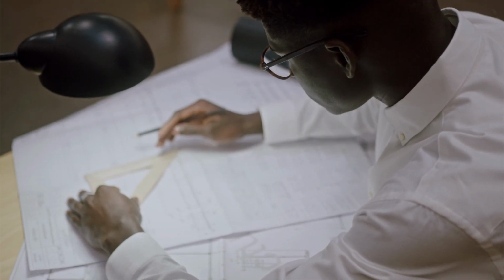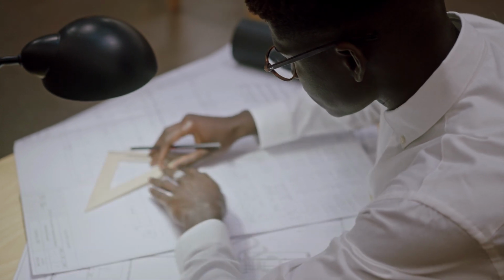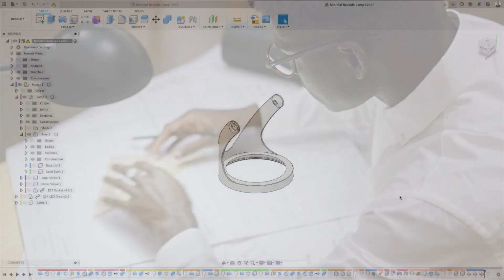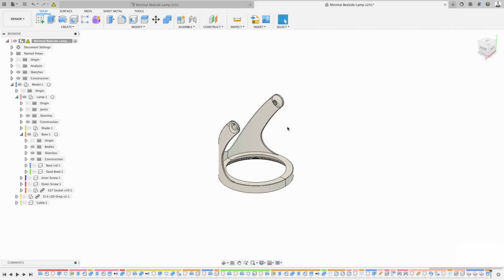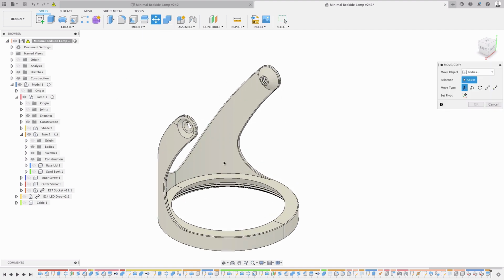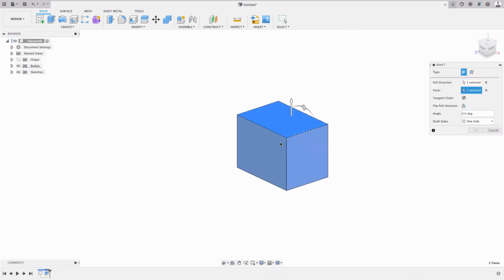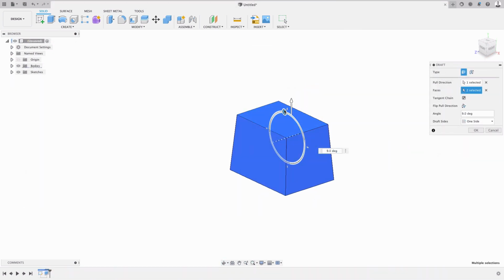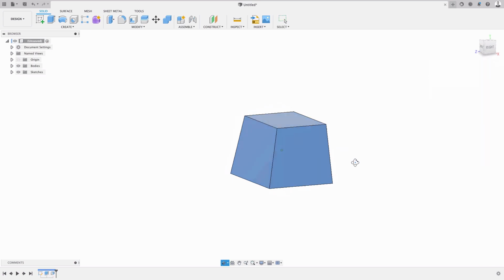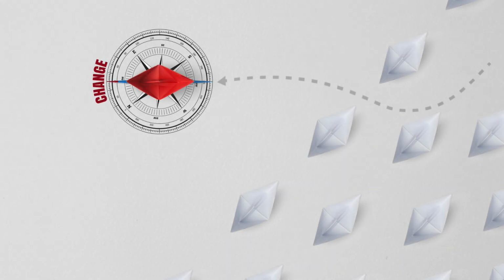And once the engineer has started working, please don't be surprised if you quite quickly run into necessary changes that will affect the external look of the product. So maybe a part that was one part needs to become two parts, or maybe some shapes need to be adjusted for injection molding, or maybe some materials need to be changed for cost reasons. Either way, this is completely normal, and I personally have not been part of any project or even heard of any project where no changes happened during the design for manufacturing stage.